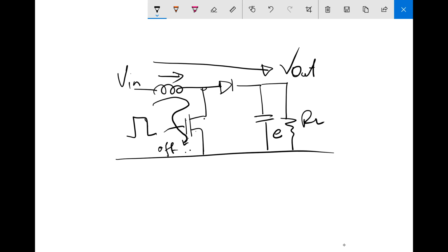As we turn the transistor off here, the voltage that is at the ground side when it is on, because there is actually a short here, will start going up. This is what we are talking about. Now let's assume that the output is 400 volt, which is very typical of, say, a power factor correction circuit.